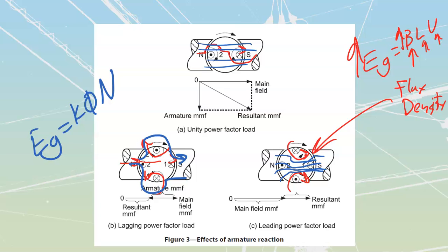Know what's laid out for you really, really simply on page 19. There are 3 bullet points. They say that the greater the load, no matter what the load is, so if it's inductive or capacitive, leading or lagging, or strictly resistive, the greater the amount of current I pull, the greater the voltage drop I'm going to have.